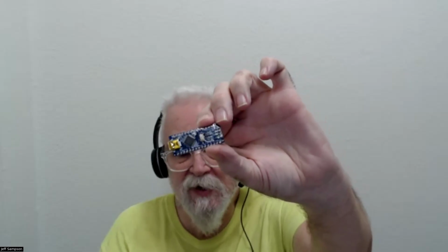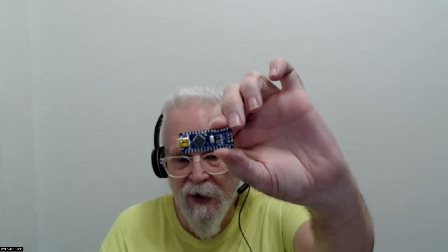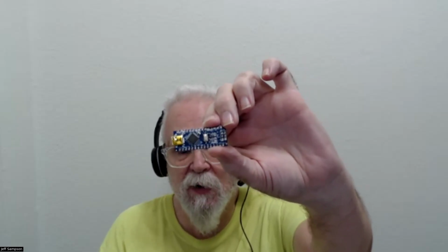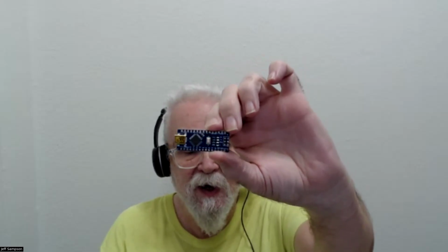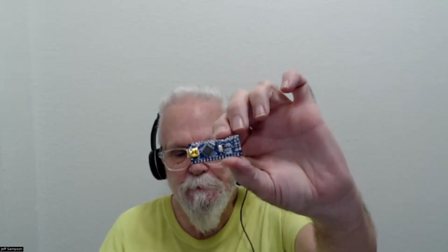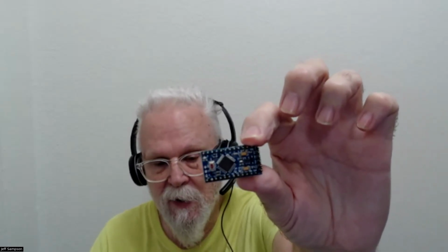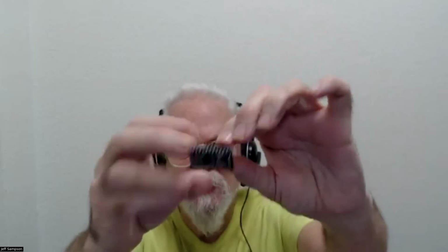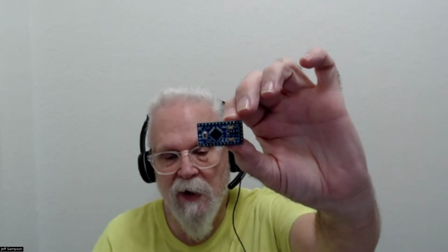But everybody says the first thing you want to do is take the power LED off this board, because if you don't, it's sucking power all the time, and it takes a couple of milliamps. So they were saying if you just take the LED off, and well, let's go to this one instead. This is the other option that I have. This happens to be an Arduino Pro Mini. It's basically just like the Uno, except it does not have the USB connector and does not have that converter chip on it. So that's one less thing drawing power. So they were saying if you take one of these, take the power LED off, and put it into sleep mode, I think it would go down to 20 microamps.